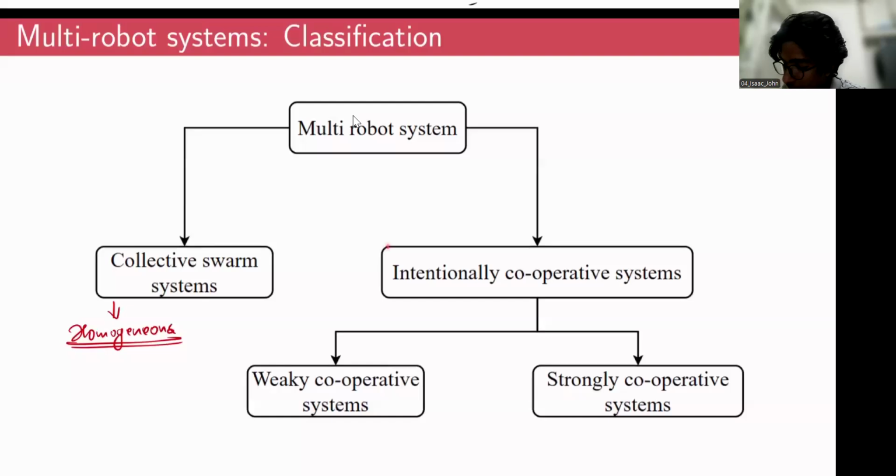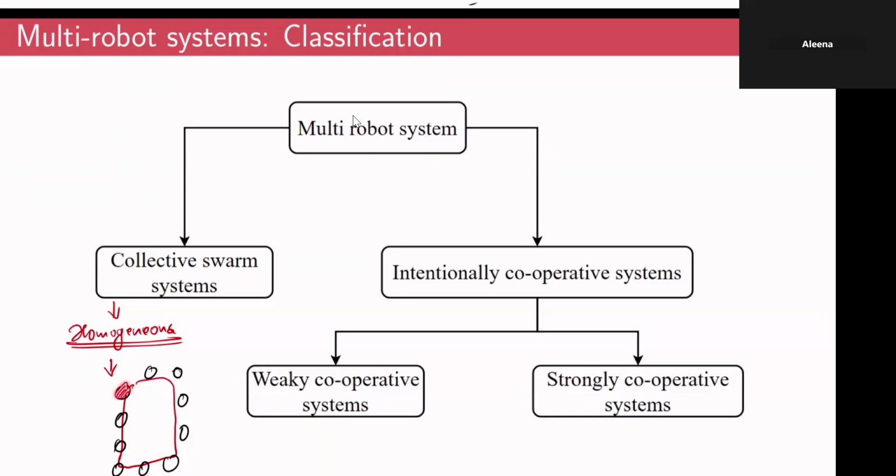And another feature is that, in swarm robotic systems, each individual member need not be aware of what the other members are doing, right? For example, if the task for a swarm system is to lift a payload by uniformly applying forces through multiple points, you could consider all these black circles as drones in a swarm system. If it is required to lift this payload, you are only required to program each member of the swarm with where it has to position itself with reference to this payload.